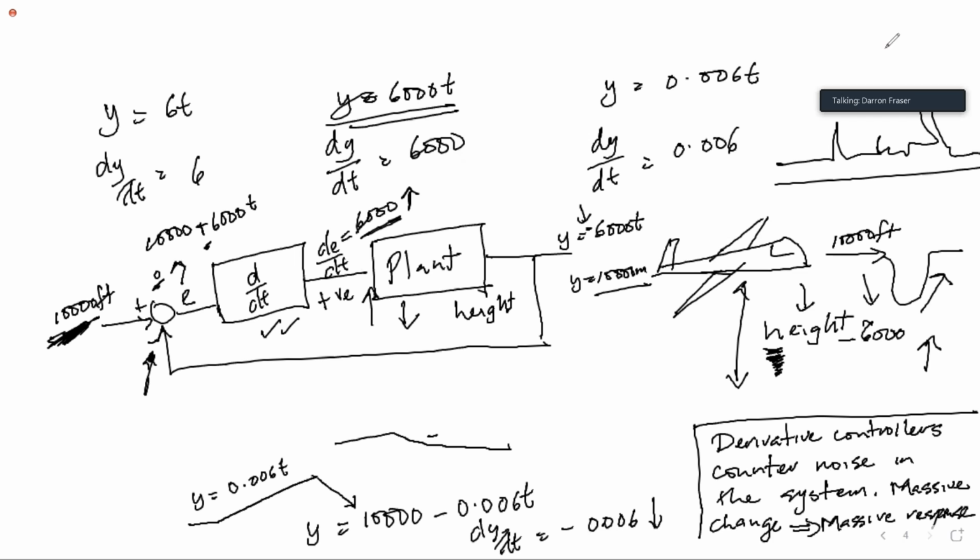How long it will take to rise, how long it will take to do X, Y, and Z. What is our settling time, what is our overshoot, and all those type of things. So we're fixing the poles so that we can do all of those. The PID controller is basically just to make sure that the plant goes to the value that we want and stays there, and it is resistant to any noise in the system.